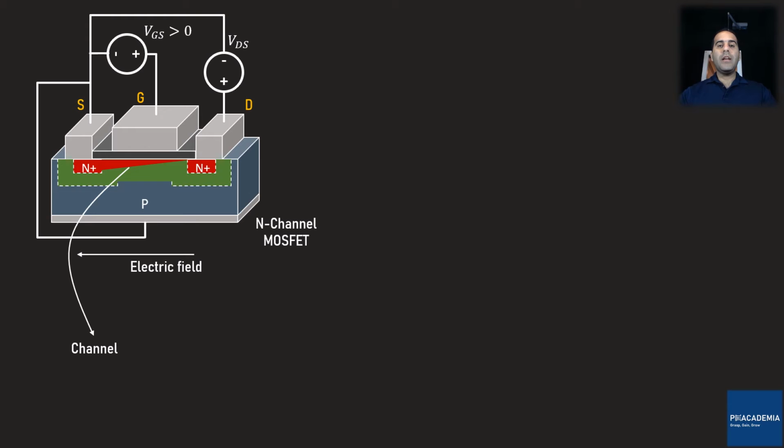By doing so, the width of the channel gets smaller and smaller. Although you may observe that the channel is not connected to the drain anymore, there is still a flow of electron currents from the source to the drain. How is it possible? It is possible due to the electric field directed from the drain to source. Once an electron in the channel gets close to the edge of the channel and depletion region, the electron is seized by the field and pushed toward the drain.